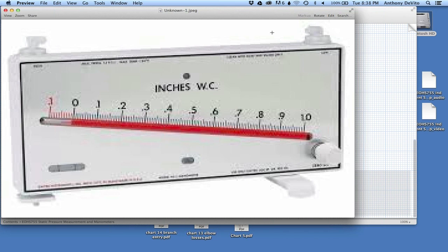Of course, if I place this side on the suction side, and leave this side open to atmosphere, the same thing would happen. It would get pulled down here. And if I made a mistake and put the suction side on this side, then this liquid probably just winds up getting sucked out of here entirely. Or the other way around, put the discharge on here.